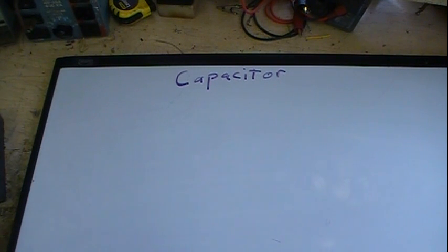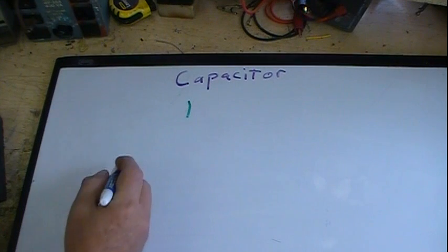You can have a vacuum capacitor, and you actually do. You work with them anytime you work on a radio or a tube radio or tube TV. The elements inside the tube are basically like capacitor plates. They're no different. They're conductors, set basically in parallel to each other, a certain distance from each other. They have a certain area. The only thing in between them is a vacuum. Not perfect, but close enough. So they act as a capacitor. Vacuum has a dielectric constant of 1.